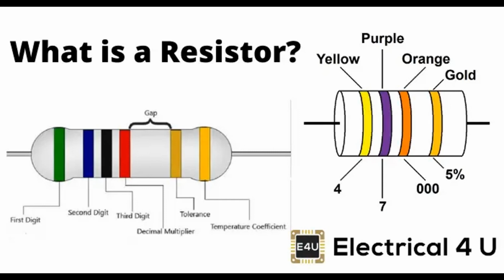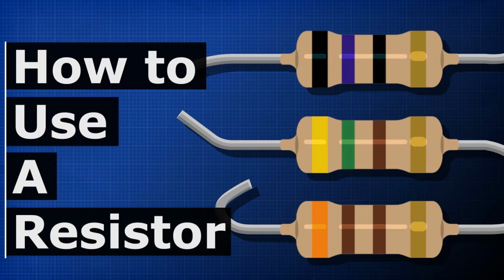Applications: temperature coefficient is a critical parameter in applications like precision instrumentation, temperature sensors, voltage references, and circuits that require stable performance over a wide temperature range. TCR, temperature coefficient of resistance. TCR is another term used to describe the temperature coefficient of a resistor. It represents the rate of change of resistance per degree Celsius and is typically specified in ppm/°C. In summary, the temperature coefficient of a resistor is a key specification that engineers and designers consider when selecting resistors for applications where temperature variations can affect circuit performance.